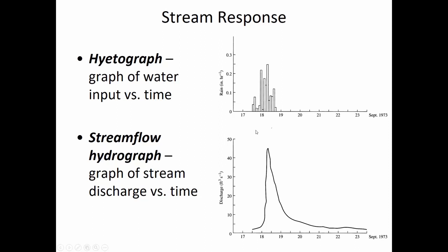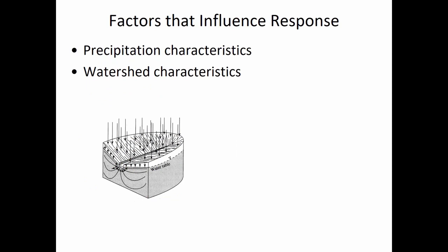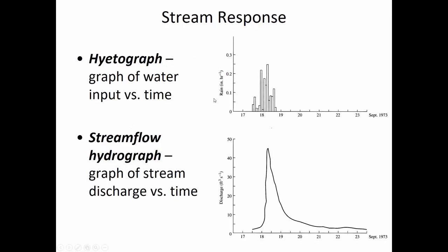And so here you can see that the time axis is the same for both of these, but the rainfall is always going to be a little bit before the runoff. And the difference between the two, the difference between the rainfall and the runoff, is the travel time, and it's how long it takes to satisfy the initial abstractions like surface storage and wetting of the leaf area and so on. There's a lot of factors that affect the difference in time between the two. There's a lot of factors that affect how big the peak is going to be.